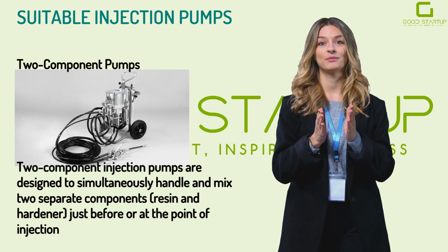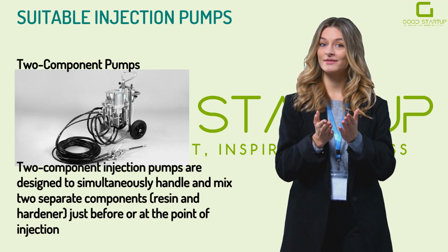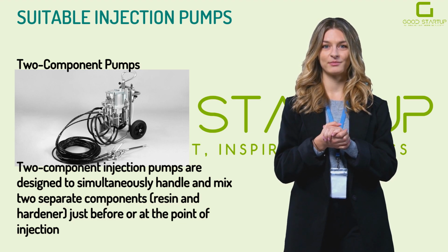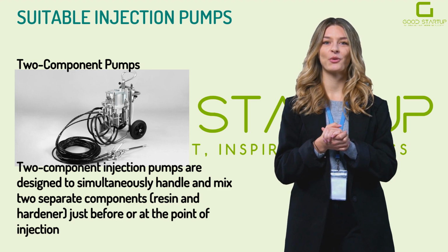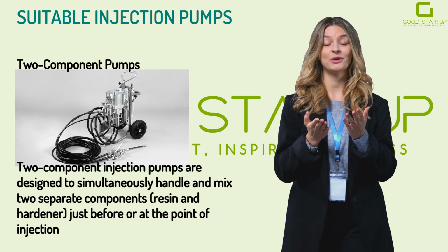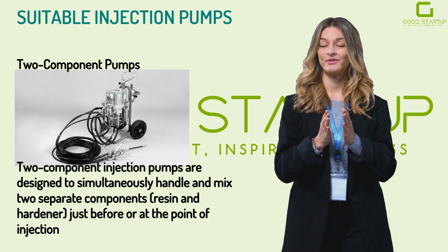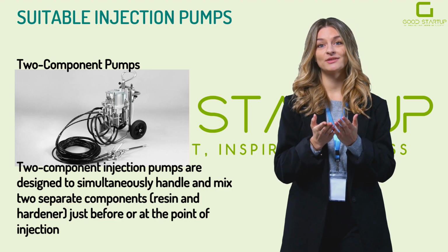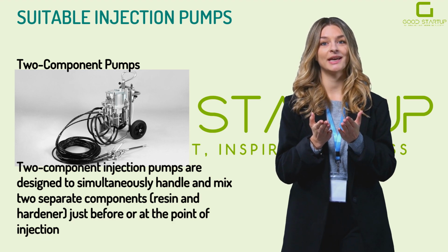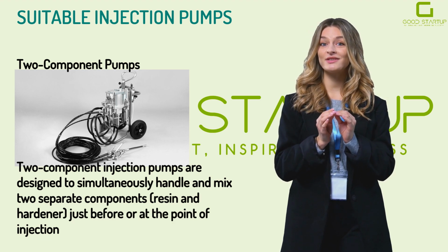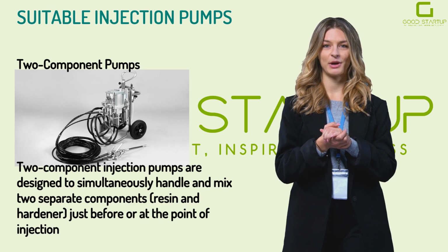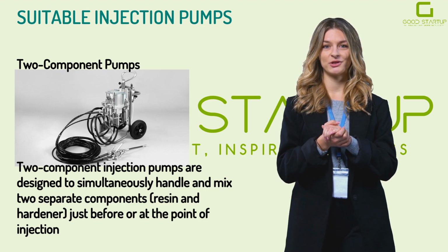They are generally powered by air compressors or electric motors and built with corrosion-resistant parts, like stainless steel, to handle reactive resins. While two-component pumps are more complex, requiring setup of dual hoses, mixer, and flush, and typically heavier, their ability to process fast-curing materials efficiently makes them indispensable for certain injections. Ease of use comes with training. Operators must understand the mixing ratio settings and maintenance, like cleaning static mixers, but modern two-component pumps are engineered to simplify these tasks, often with disposable mixers and quick flush features.